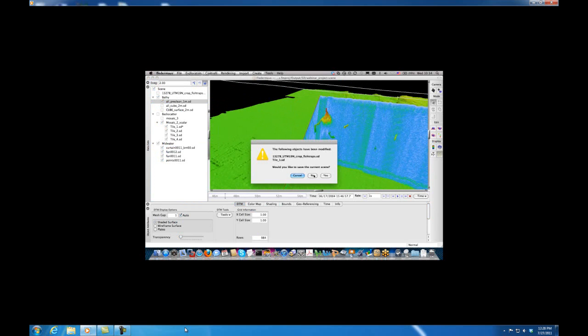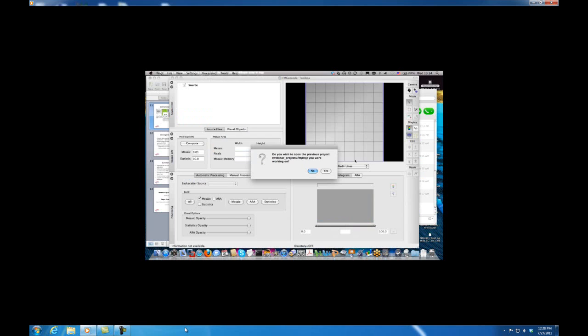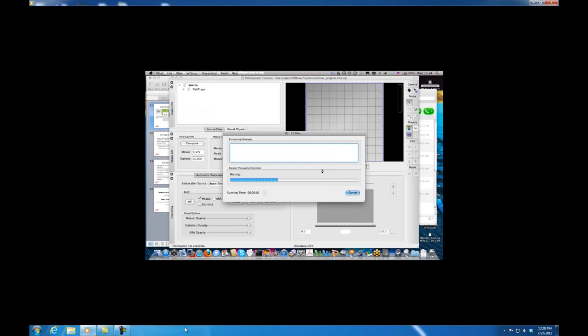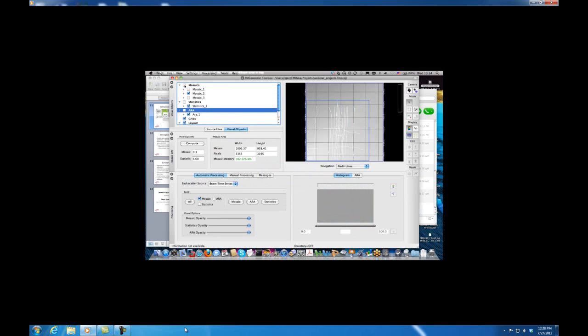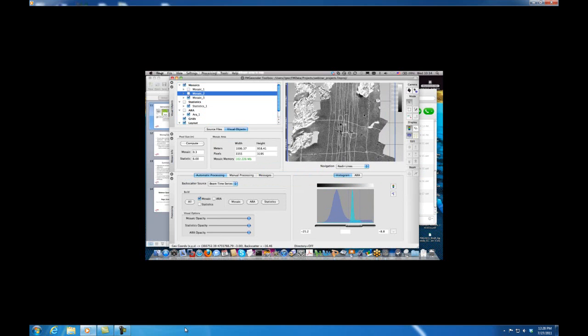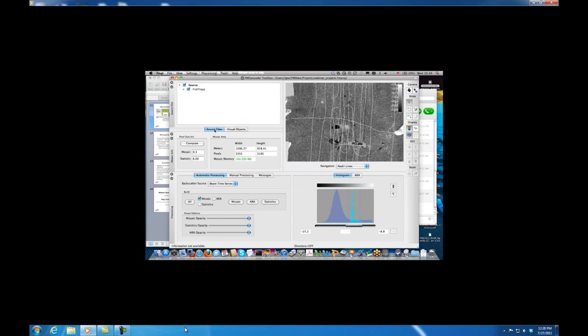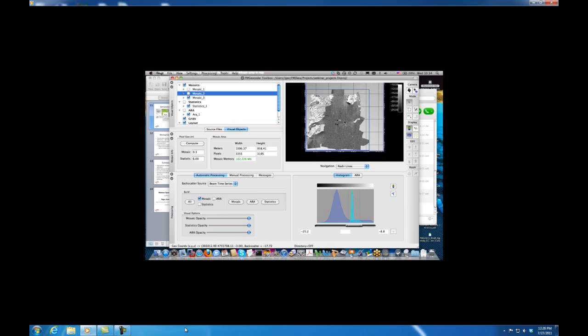One thing I forgot to say: in GT and how we use the data together is one of the issues you might have in backscatter processing. A good example is the fish traps, which actually affect some of the processing. Let me turn the source data off here for a minute. You can see the fish traps are affecting some of the backscatter processing because all of the pings have been used.